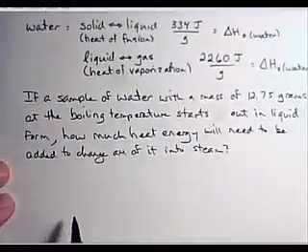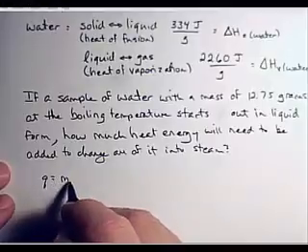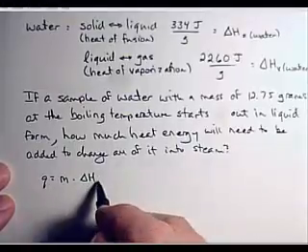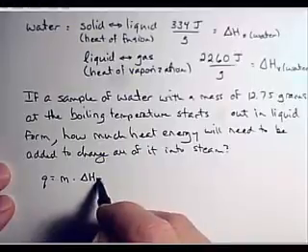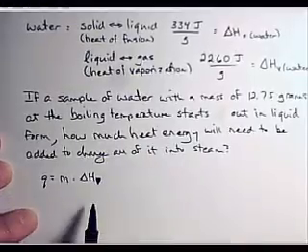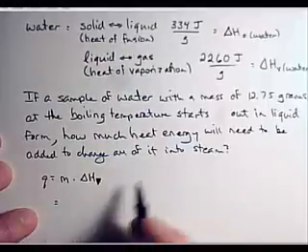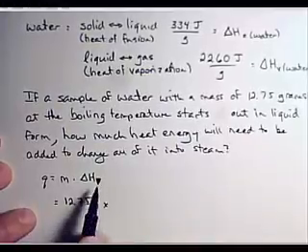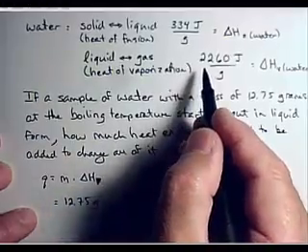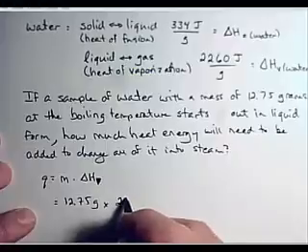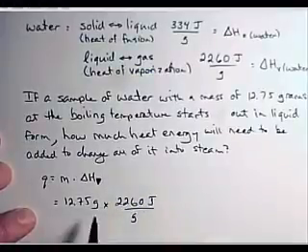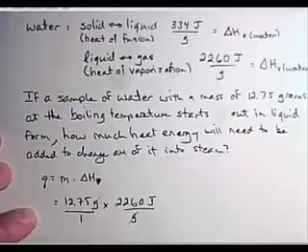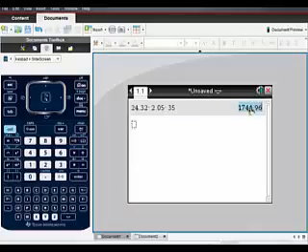Well, for that, then, we're only using this equation, Q equals mass times the change in enthalpy for this physical state change, and this physical state change is, I'm sorry, not F, but V. Okay, this is vaporization. So the mass is 12.75 grams. The change in enthalpy for vaporization is 2,260 joules per gram. Okay, put this over 1, cancel out grams, and do the math. Multiply. Pretty straightforward, pretty simple, really.